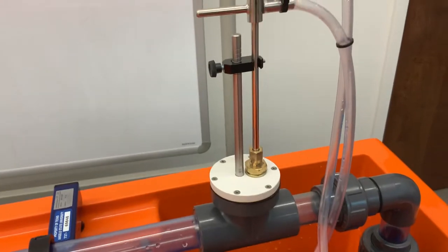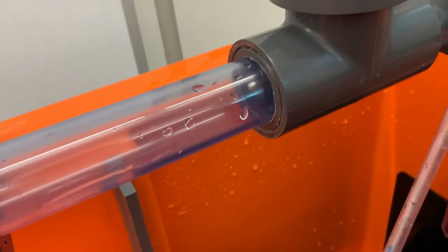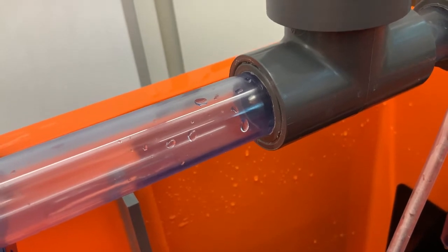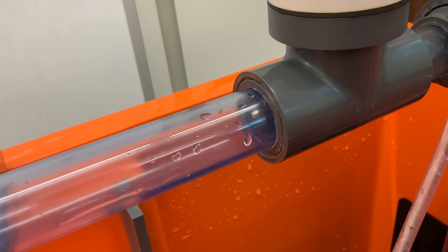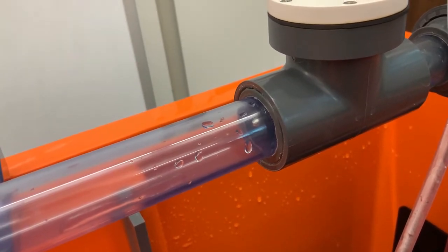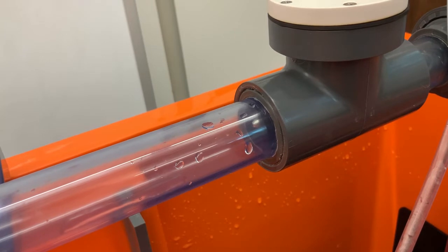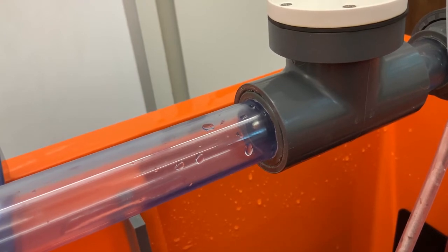The Pitot tube, how it works, you already know, is that it has an opening at the point and then openings on the sides. So at the face point, you have the summation of the static pressure, which is the same for every position in the liquid or water and the wall, plus the dynamic pressure.